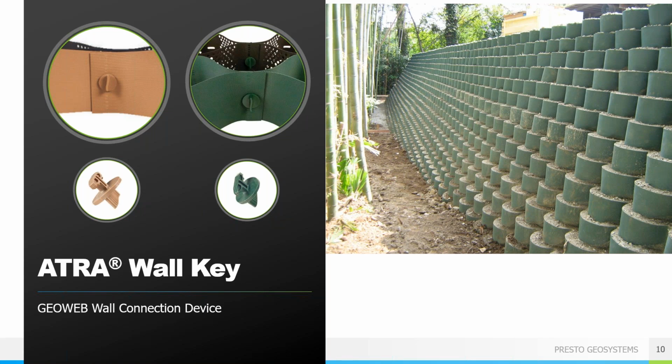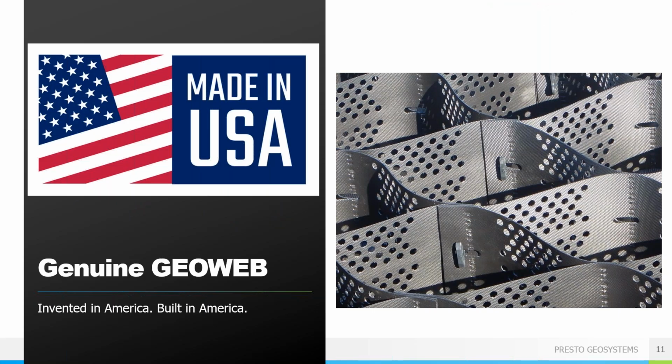So we used to use metal staples, back in the day, and even looked at some zip ties. But over time, those metal staples are going to degrade, corrode. You can have separation of panels. Zip ties don't provide a secure connection. So just be aware when you're looking at different types of systems.